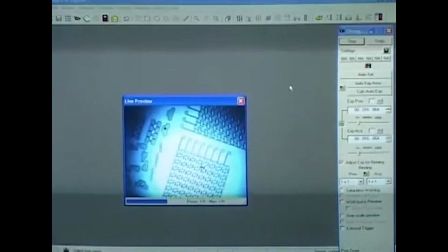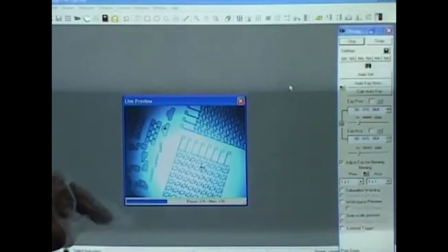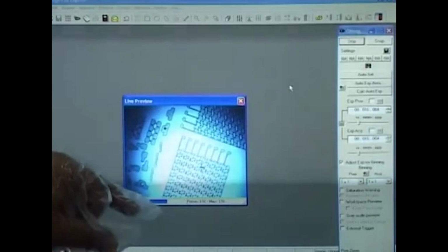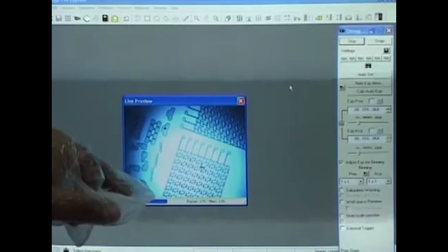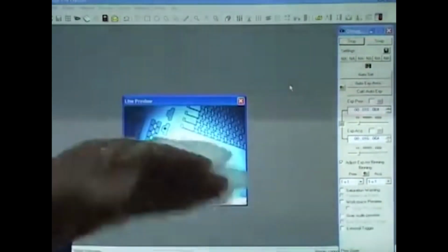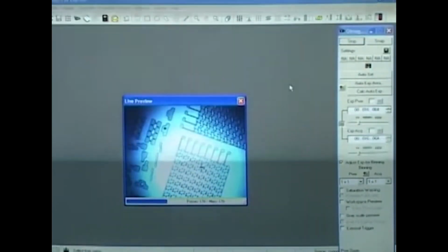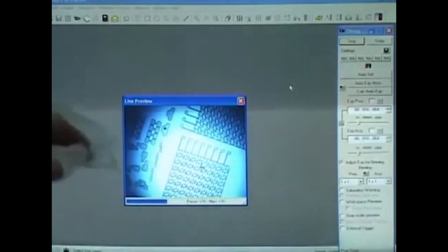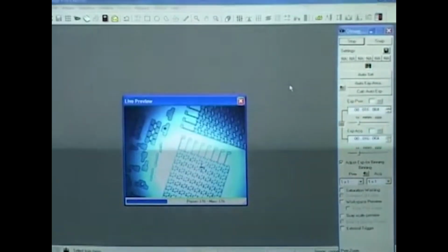So, I would actually be able to first see the preview here from this option, and if I click on it, as you see, this is really the image that I was wanting you guys to see. This is something that we have developed using photolithography onto the surface of the wafer. Now, I will be doing the dimensioning part in a little bit, but suppose it is out of focus or in focus, you can change the focusing stage on the microscope, as I told you, and get a very good focus on these images. Now, this is probably one of the best foci that one can get using these images, because I have already calibrated it using the eyepiece.